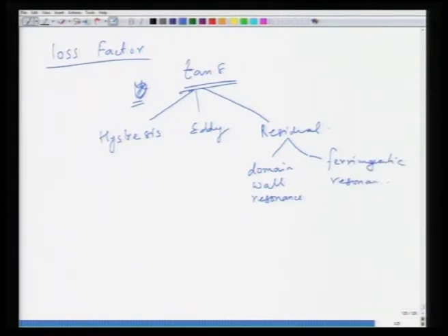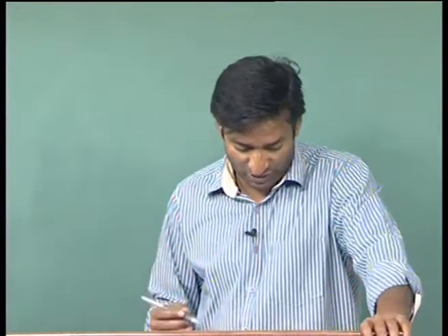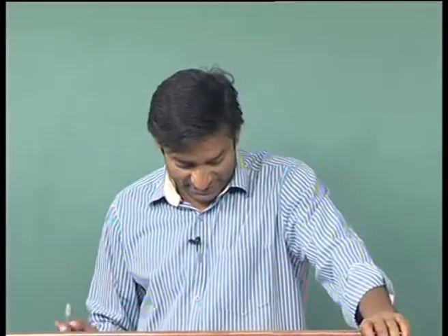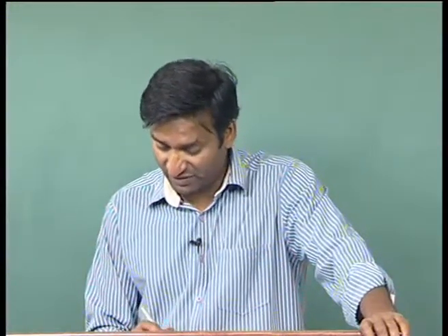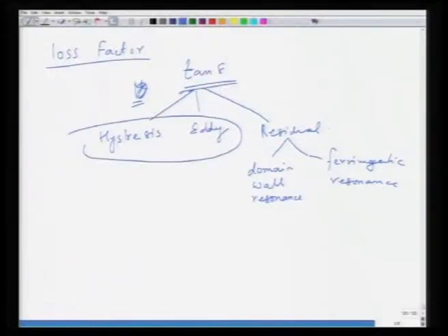simply because permeability is a complex property. So when you look at it as a function of frequency, you are going to have a resonance. And typically in the high resistivity ferrites, where hysteresis and eddy current losses are low, the residual losses can be quite high, and this can lead to a lot of problems. And this has essentially been related to domain wall motion.